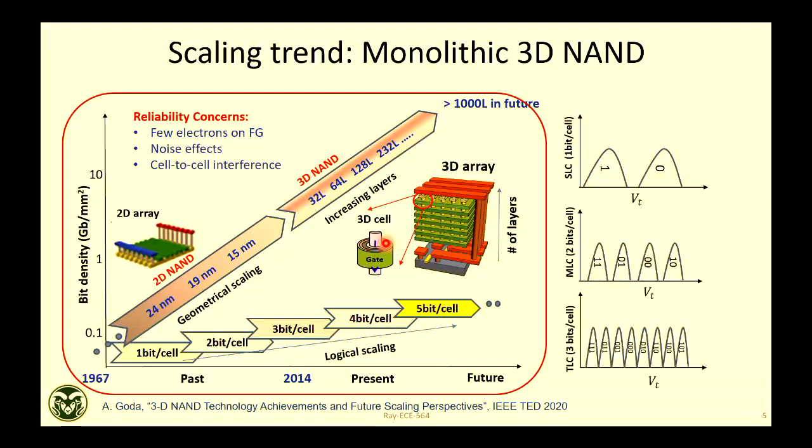Okay, so this is the logical scaling, 3-bit, 4-bit and all, right? So higher the bit density, if you increase the bit density, you'll degrade reliability. So reliability was degrading, but then there is a jump: with 3D NAND, reliability again improved, because now cells are a little bit bigger.